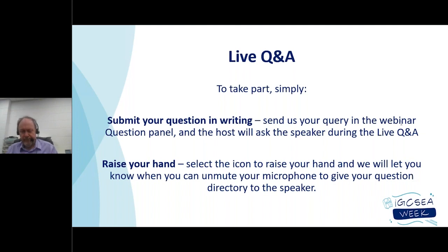Yeah, that's a great question. I would say if moisture is not changing the surface, let's say a hydrophobic surface, you add water, you're going to get very little change. You might just see, like Daryl said, a small decrease in the surface energy. However, for a lot of real world materials, moisture changes the properties of the material. It could open up different functional groups. It could cause an amorphous to crystalline transformation.